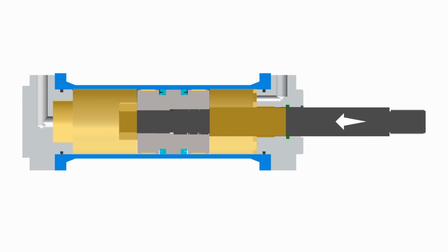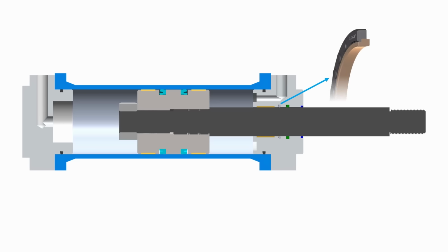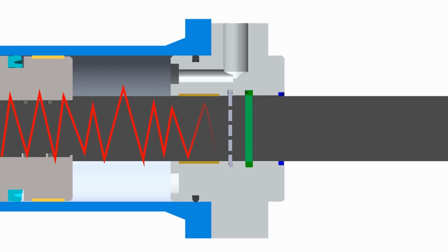Now, in a hydraulic cylinder, abrupt pressure peaks can occur due to external force acting on the piston rod or initiated by the fluid inside the cylinder. And these pressure peaks can far exceed the system operating pressure, which can cause the main rod seal to leak. So in such cases, we use a buffer seal before the main rod seal. What a buffer seal does is not fully seal the pressure, but reduce the peak intensity of pressure, acting as an intermediate seal before the main seal.